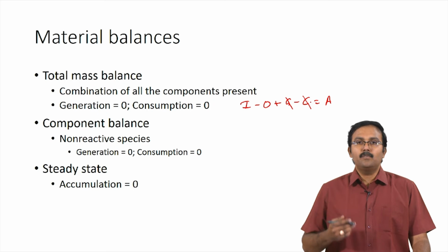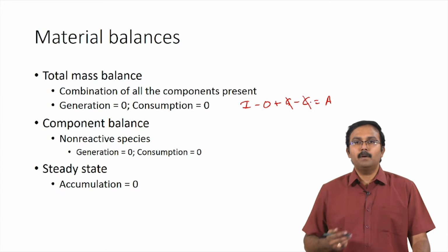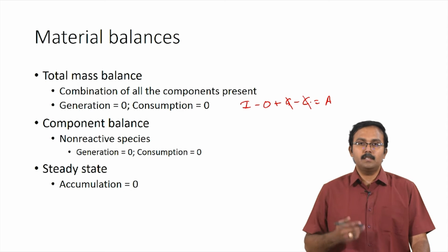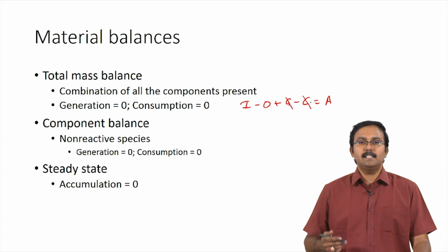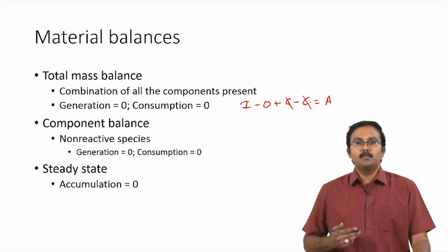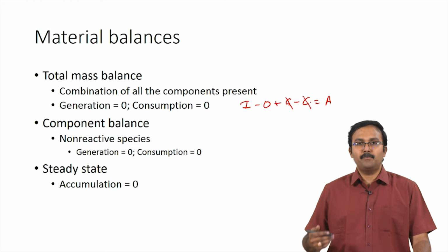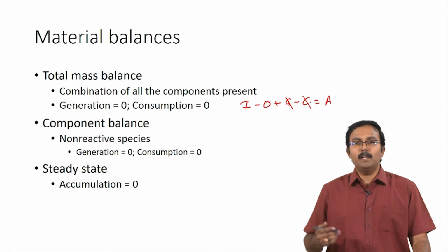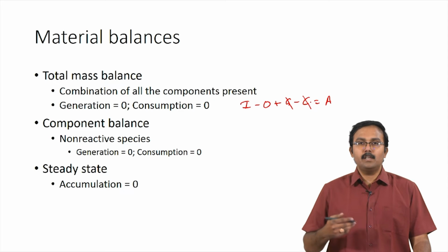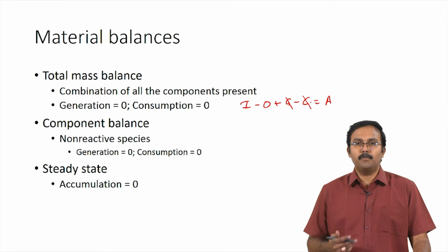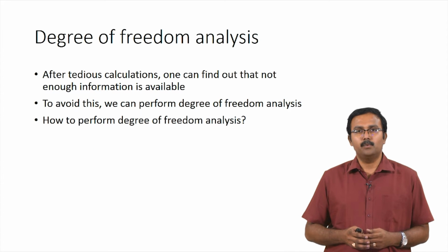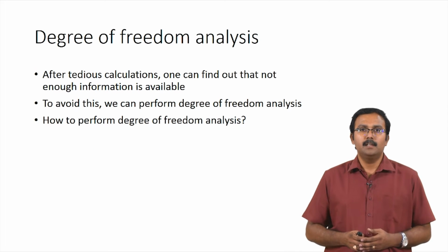Other times you actually have steady state operations. For this reason, for all the calculations which we perform for the material balances and even for energy balances, we will assume the system to be at steady state unless it is explicitly stated otherwise. So, please remember this, and whenever I perform calculations in the subsequent lectures, I will be assuming accumulation to be 0 even if it is not stated in the problem explicitly, because we will be assuming steady state for performing the calculations.